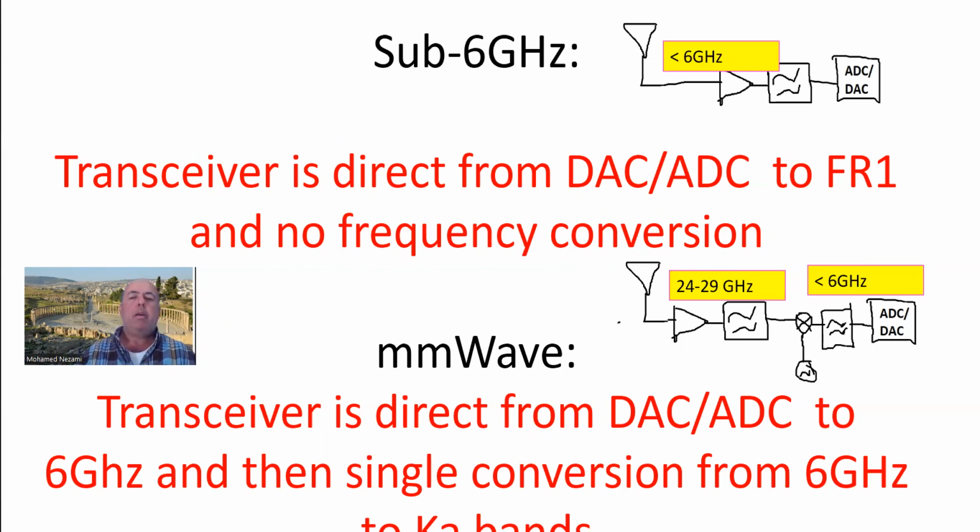We can go directly from bits to antennas using high-speed ADCs and DACs. And we know that these nowadays are available with DAC sampling rates up to 12 gigasamples per second. And then we have ADCs that are available all the way up to 8 gigasamples per second, even more in some cases, commercially from various sources like E2V, Analog Devices, Texas Instruments, all of those guys deliver these.